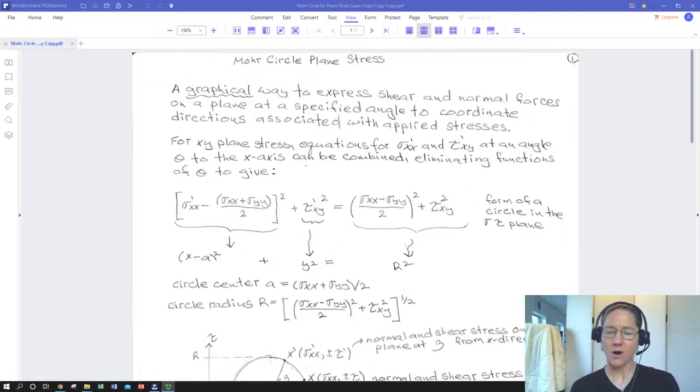So we have already covered in a previous lecture the shear stress transformation equation, where we took a slice of material from inside a body with a plane that was tilted with an angle theta with respect to the x-axis, and we put it in static equilibrium, including a normal stress and a shear stress that was appropriate to that tilted plane. And just as a reminder, when we talk about angles of a tilted plane, we're talking about the angle that the surface normal to that plane makes with some designated axis. And in general, it's always going to be the x-axis.